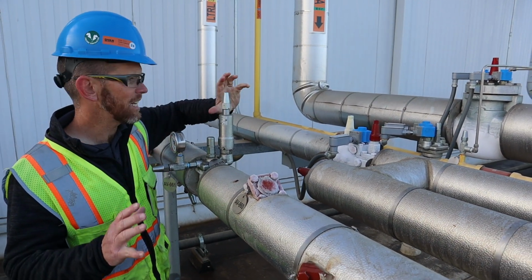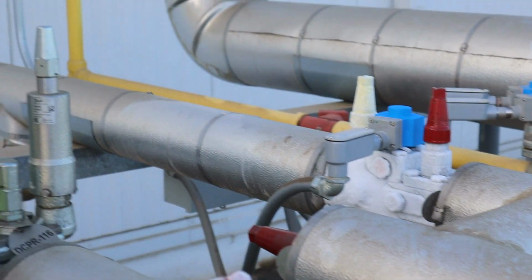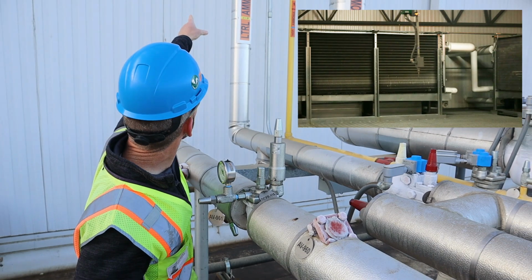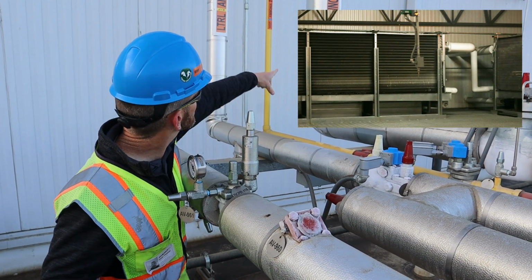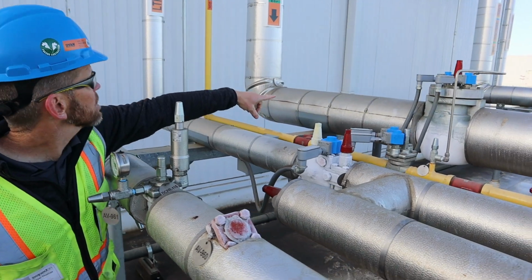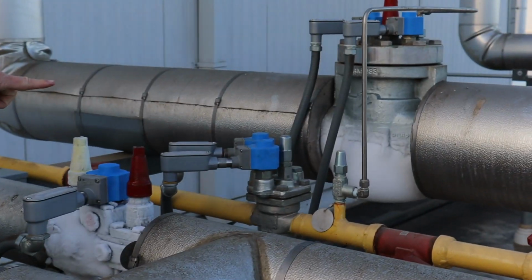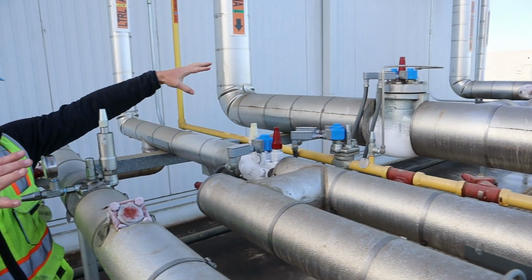Now, under normal conditions, liquid will be flowing through this solenoid valve based on the temperature in the room. Liquid goes into the evaporator, the fans pull air over it, causing that liquid to boil. It exits through the suction pipe labeled LTRS, through the suction stop valve into the main, which takes it back to the recirculator in the machine room.